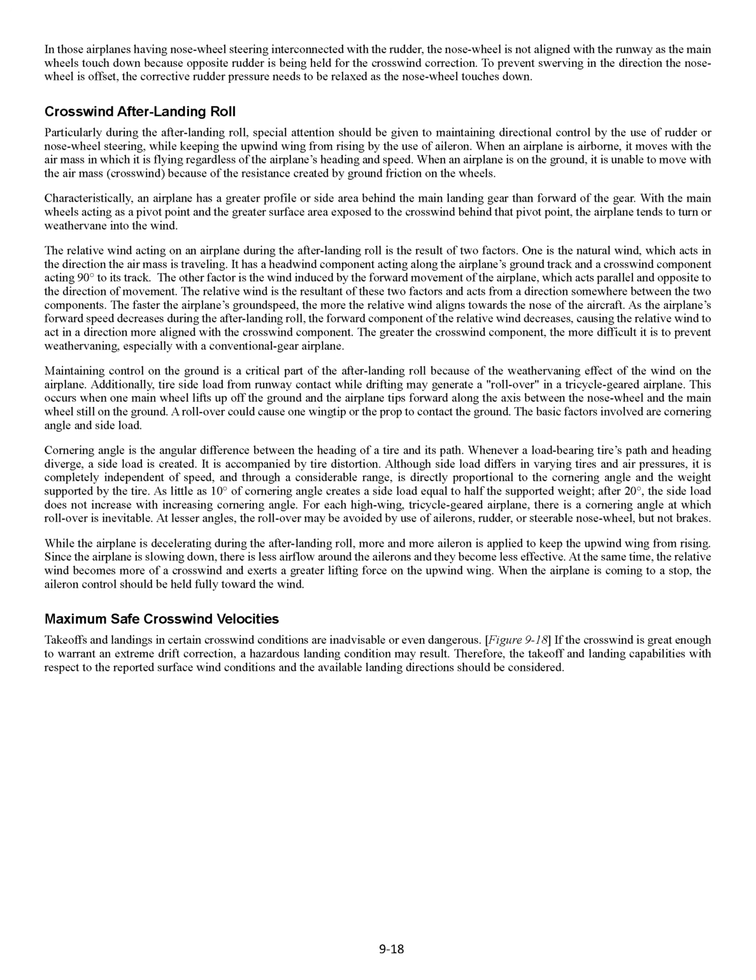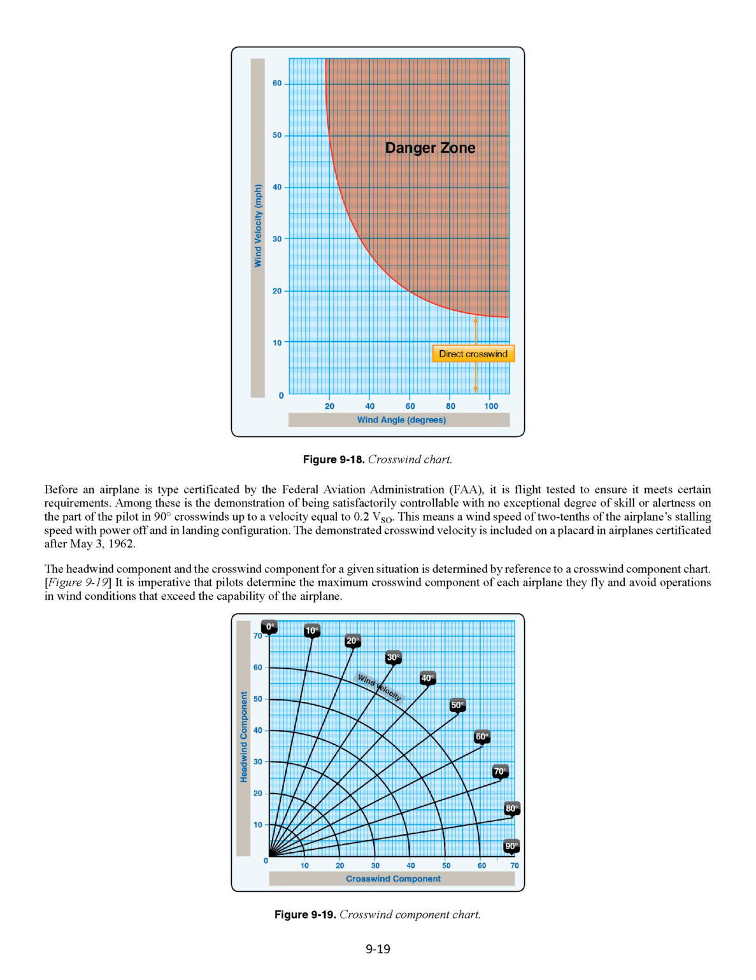Maximum safe crosswind velocities. Takeoffs and landings in certain crosswind conditions are inadvisable or even dangerous. If the crosswind is great enough to warrant an extreme drift correction, a hazardous landing condition may result. Therefore, the takeoff and landing capabilities with respect to the reported surface wind conditions and the available landing direction should be considered. Before an airplane is type certificated by the Federal Aviation Administration, FAA, it is flight tested to ensure